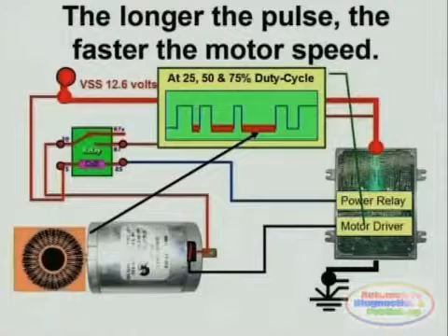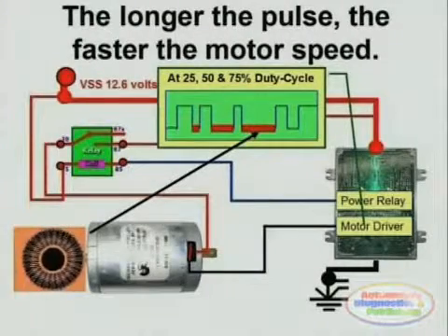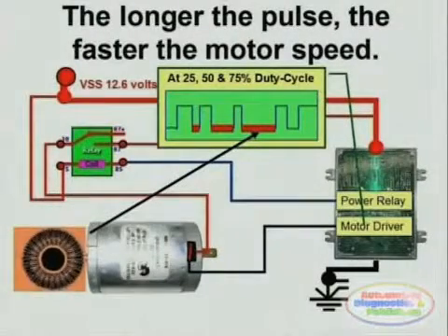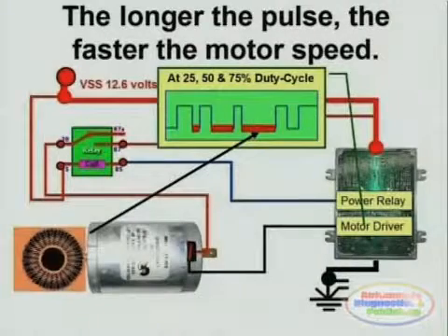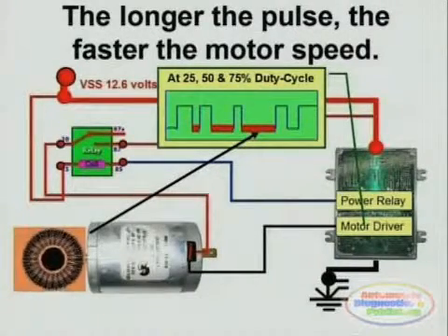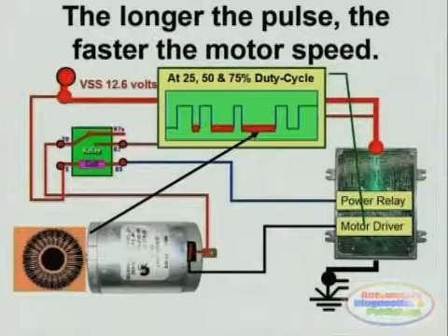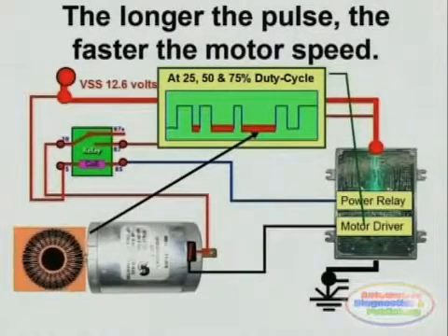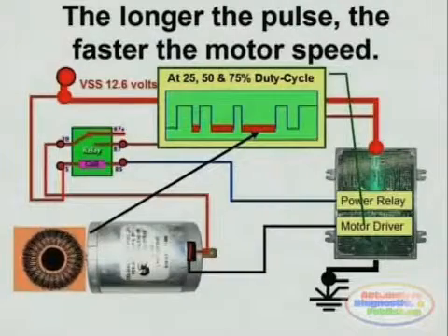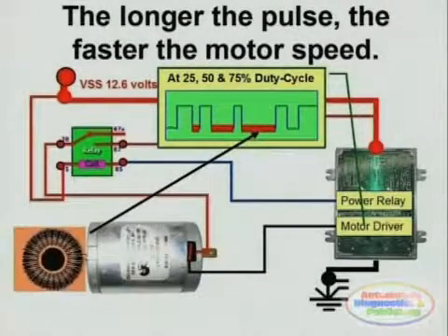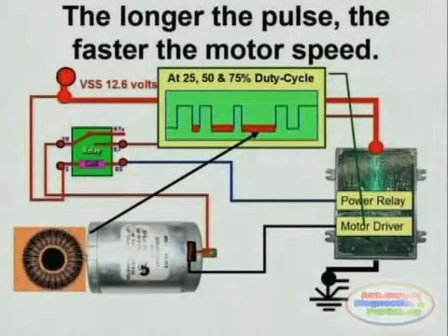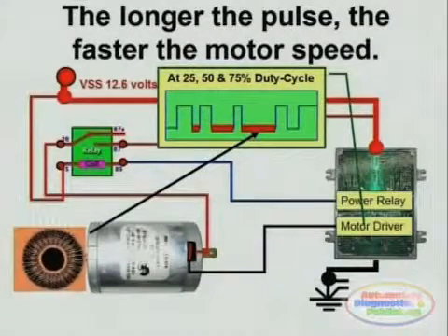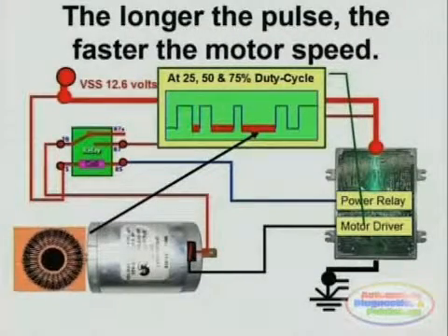The output of the controlling circuitry is going to be determined by the width of the pulse that is applied to the base of the transistor doing the controlling. This pulse is modified by the microprocessor through its internal circuitry, and the microprocessor, through the transistor driver, determines the speed of the component being controlled.